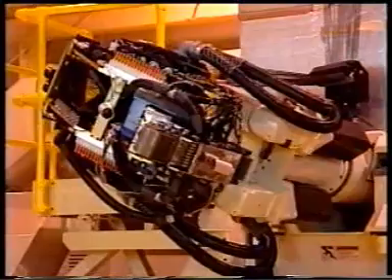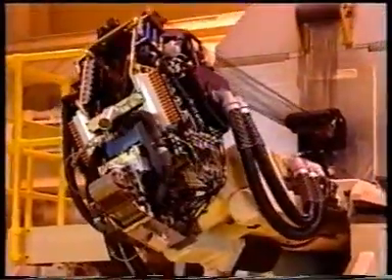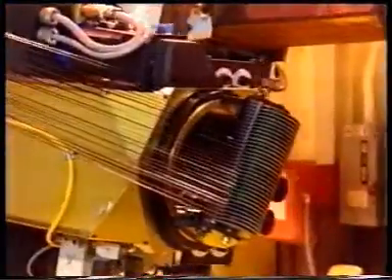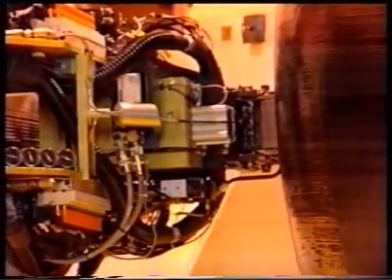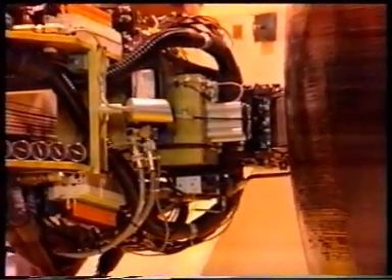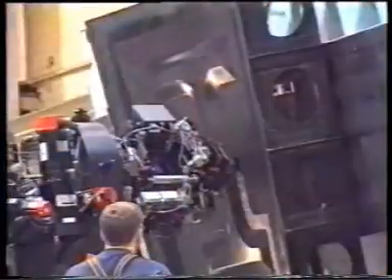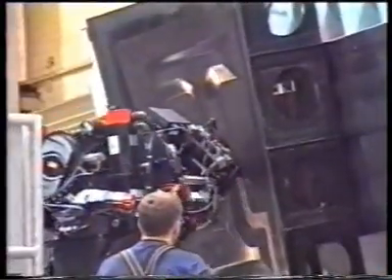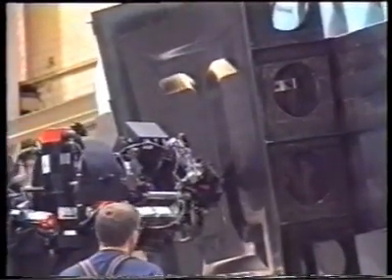To overcome the limitations of tape layers, automatic, multi-axis fiber placement machines were introduced. The machines automatically control dispensing numerous individual narrow tapes of material, which are collimated as they are laid on the mold surfaces. Each tape can be independently dispensed, clamped, cut, and restarted during fiber placement. As a result, parts of compound curvature with convex and concave surfaces and small bend radii can be produced.